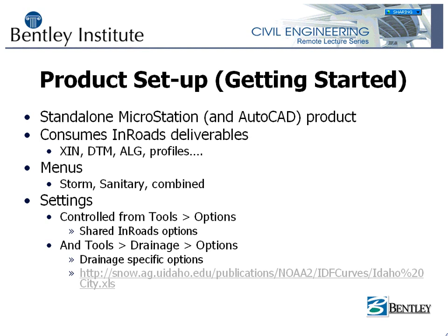So, getting started. The first thing to realize is that Storm and Sanitary is a self-contained product in itself. Its only prerequisites are a CAD engine to run on, MicroStation, or if you insist, AutoCAD, but being a good Bentley citizen, MicroStation is the one you want to run on. It will, if available, consume any deliverables that InRoads provides, such as the XIN files from InRoads, the DTM, ALG, profiles, anything that you generate within InRoads, Storm and Sanitary can use.